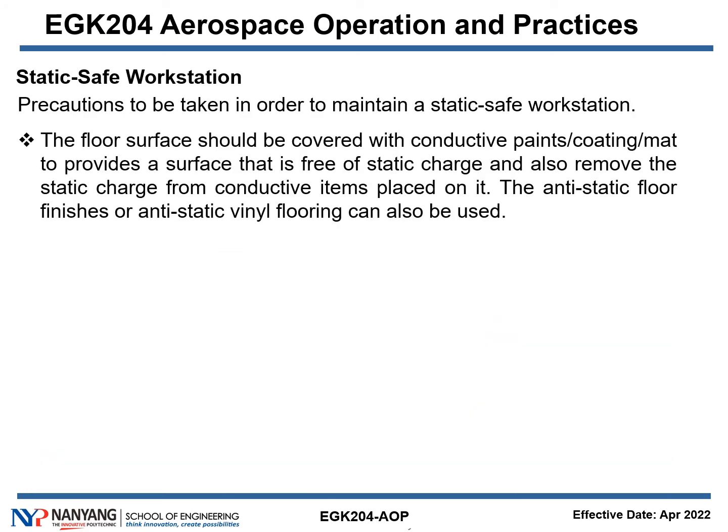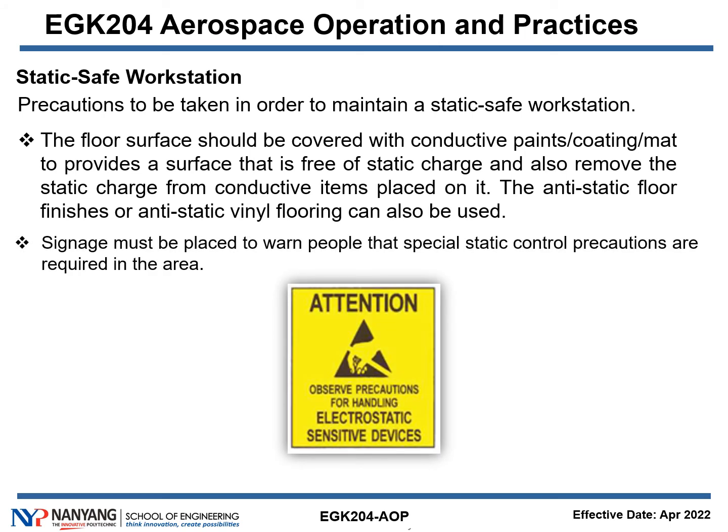Then the floor is to be covered with conductive paints, coating or mats to provide a surface that's free of static discharge. And then you must place a sign to warn people that these static control precautions are required in the area so that they will know.